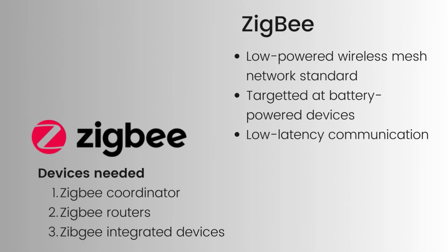Any device such as a refrigerator, air conditioner, dishwasher, washing machine, roller gate, fan, or a smart bulb that wishes to connect with a Zigbee network must have a Zigbee module integrated into that device. These modules are connected to Zigbee routers, which in turn connect to the coordinator. Through the coordinator only, the mobile apps that are built to manage and control Zigbee modules communicate with the different Zigbee enabled devices.